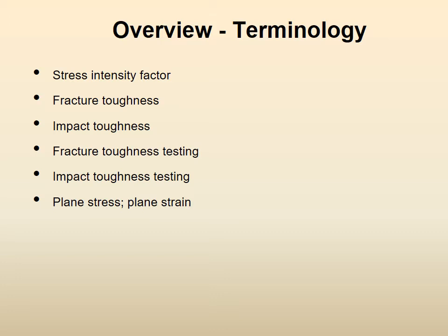Now it is called a stress intensity factor, because here you are saying that you will study the type of crack that is there, right? The type of crack: it is a straight line, it is round, it is elliptical, how the load is applied and so on. So the crack geometry and the type of loading together will tell us how much stress intensity there is near the crack. So this will be called a stress intensity factor, and this will become the beginning, the basis of all my fracture mechanics calculations. Okay?